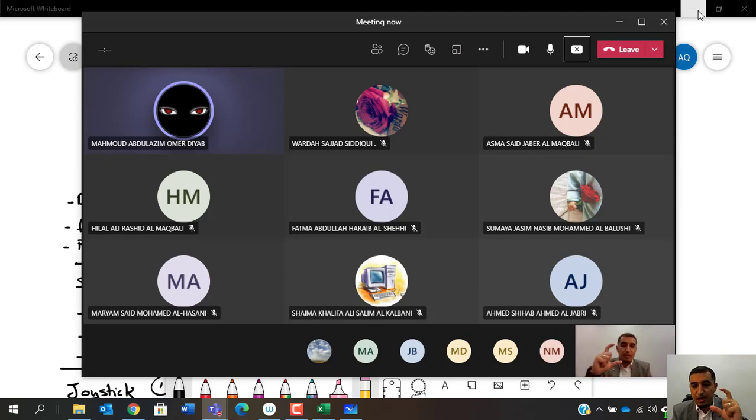No. Just get the keypad. There is a module for the keypad. Connect the keypad, make sure it's working. This is one part. Then connect the LCD. If I was you, I first would start with the LCD. So I will put the LCD, make sure that the LCD is displaying a message. Then I will add a keypad. Keypad, the output will be LEDs. Then I will connect the LCD and the keypad to one system. If it's a door lock, you need a motor to open the door and close it. You need also to connect a motor.